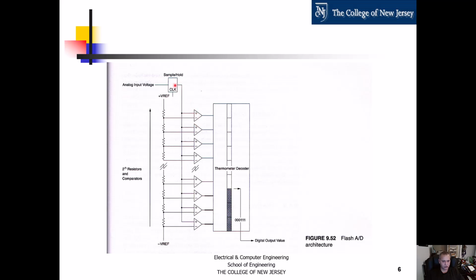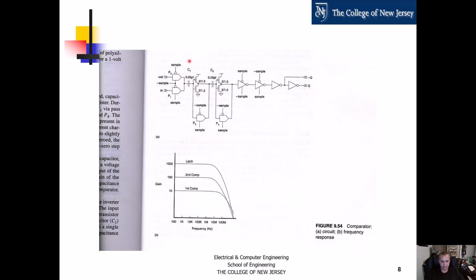So the clock and the holding is built and replicated, but this is an abstracted view of the A to D. And that piece here, the sample and hold, is here with the capacitive sampling, and then we have sort of a latch here with the capacitance, and then we basically buffer it out, what we call Q and Q naught outputs.